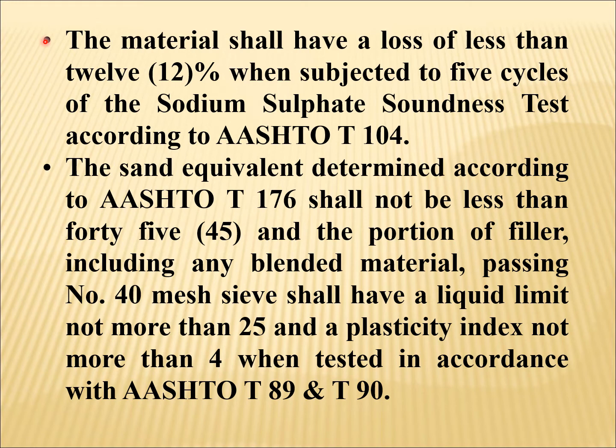The material shall have a loss of less than 12% when subjected to 5 cycles of sodium sulfate soundness test according to AASHTO T104. The sand equivalent determined according to AASHTO T176 shall not be less than 45, and the portion of filler including any blended material passing number 40 mesh sieve shall have a liquid limit not more than 25 and a plasticity index not more than 4 when tested in accordance with AASHTO T89 and T90.